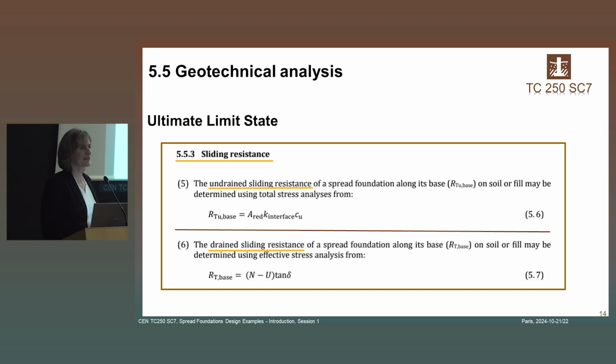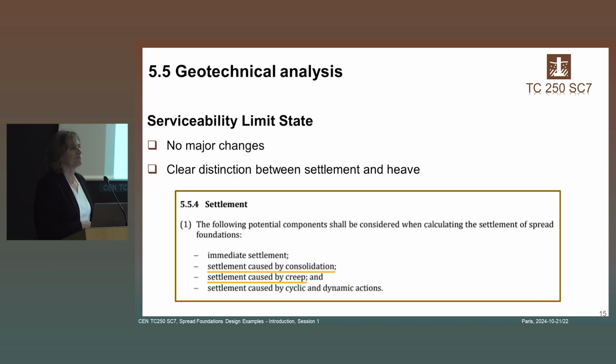Also the sliding resistance, so everything before dealt with the bearing resistance. With the sliding resistance, we have again the differentiation between the undrained and the drained resistance. But this is, let's say, nothing new from the methodology. Also, as with the bearing resistance calculation, this is what you know already. So just from the presentation in the code, maybe it looks a little bit different at first view, but in the end, the way to calculate the bearing resistance is more or less the same, but you have more clear regulations on how to do that.